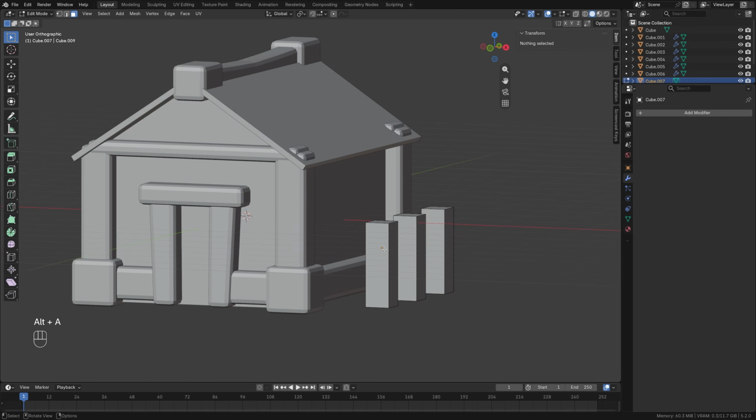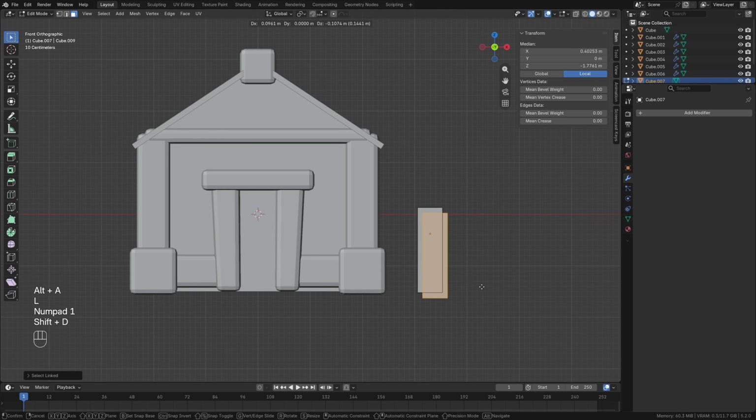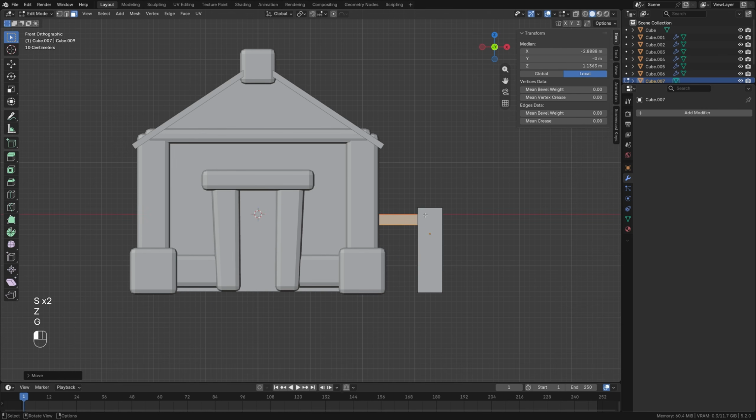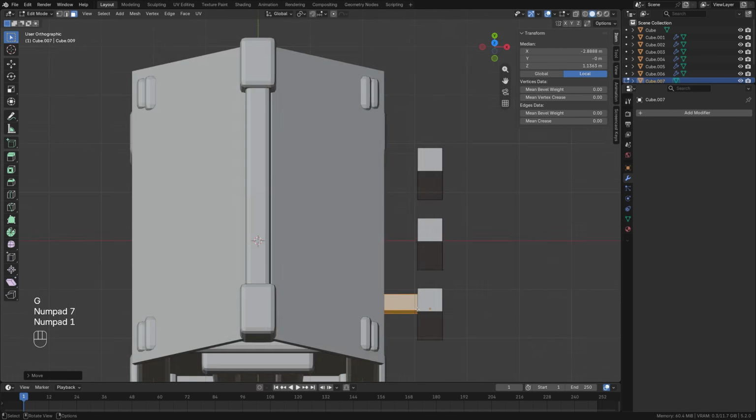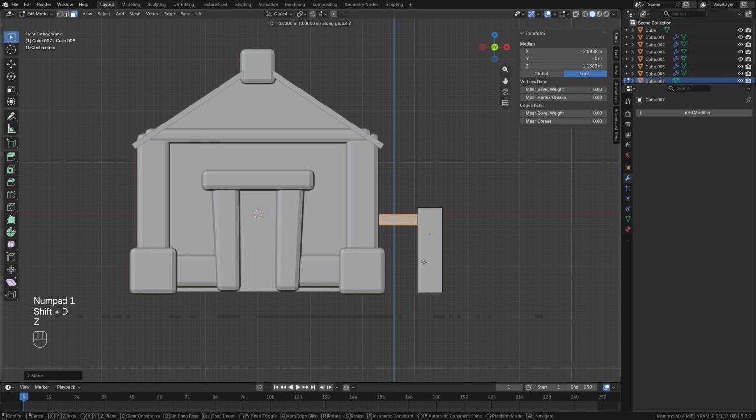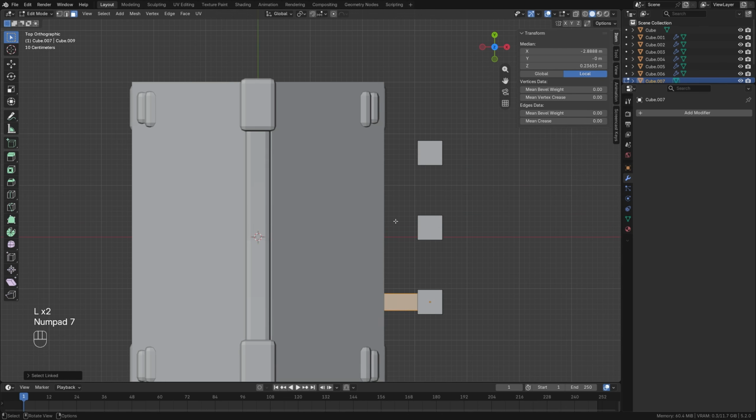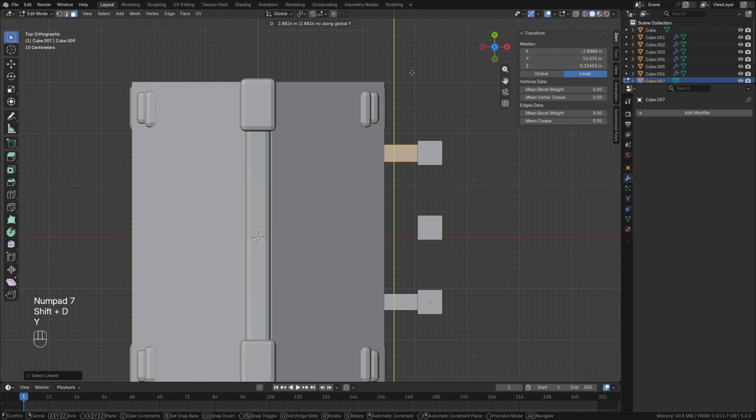And now from this same cube, you can select and on front view, duplicate, rotate by 90 degrees, make a little smaller, and also along the Z-axis, reduce and place in this area. We look on top view. Excellent. And now we duplicate down along the Z-axis. And here already, S plus Z. And we make this part a little bigger. We select both of these elements. We duplicate them along the Y-axis to this side. And one more time we duplicate. We rotate by 90 degrees and place here.